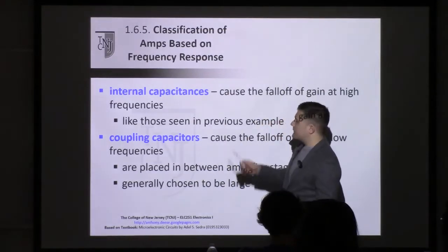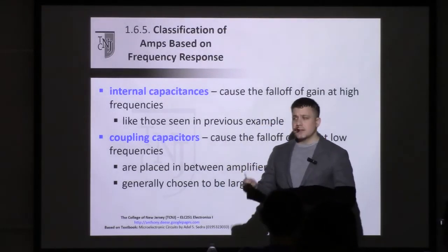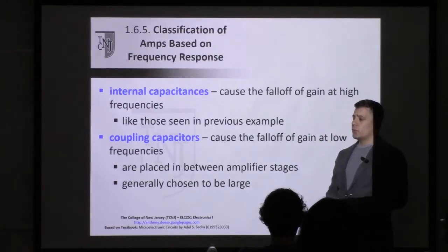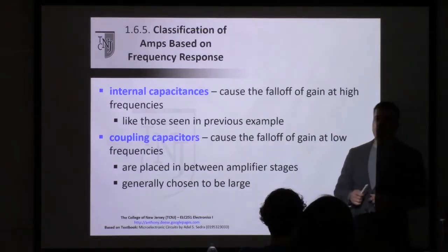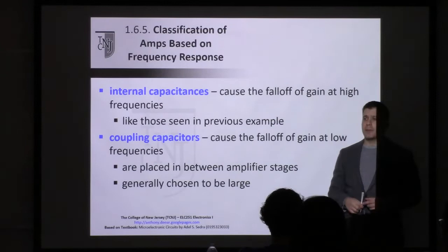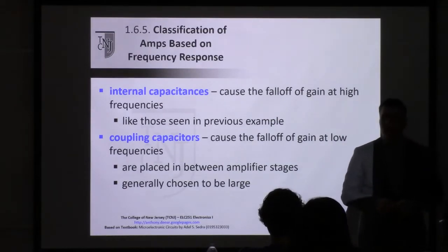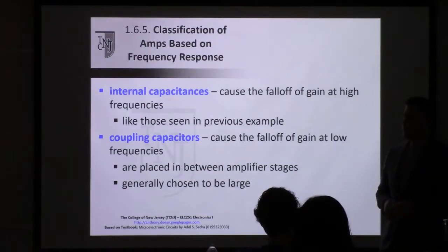And so you have the gain fall off at high frequencies. This is something you often see in real-life amplifiers. Real amplifiers often do have a capacitive input characteristic, which means that to work at really high frequencies, you will need better and better amplifiers.